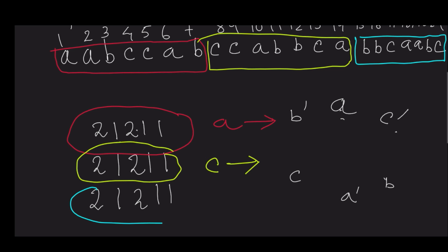like this one, first 2 are occupied by your B, and this is the B group coil, first 2 B, next one C, next 2 should be occupied by, after C what phase should come, again A, so next 2 should be occupied by A, this is basically 2A, then 1B, 1C. See how beautiful and how enticing these things are, that you have got an arrangement number,